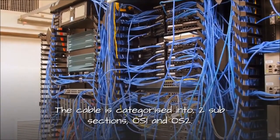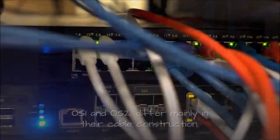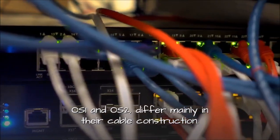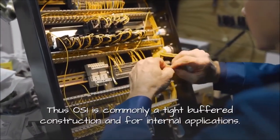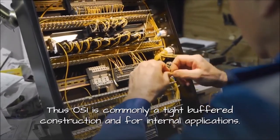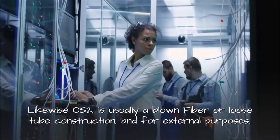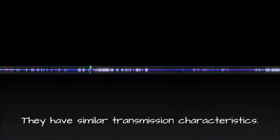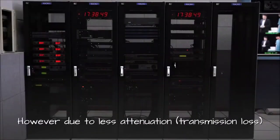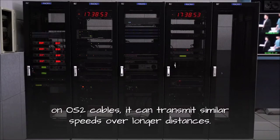The cable is categorized into two subsections, OS1 and OS2. OS1 and OS2 differ mainly in their cable construction. Thus OS1 is commonly a tight buffered construction and for internal applications. Likewise, OS2 is usually a blown fiber or loose tube construction, and for external purposes. They have similar transmission characteristics. However, due to less attenuation, or transmission loss, on OS2 cables, it can transmit similar speeds over longer distances.